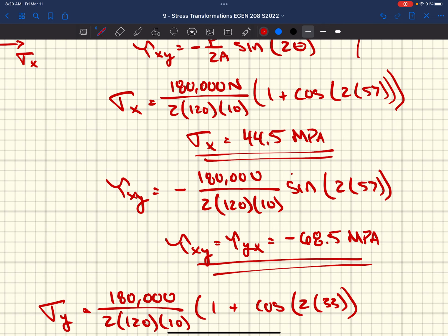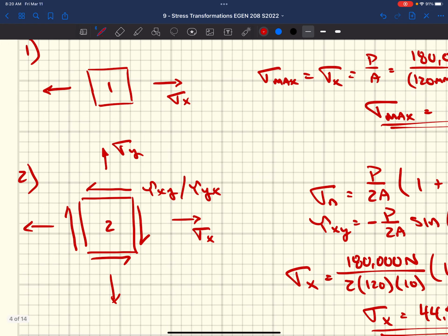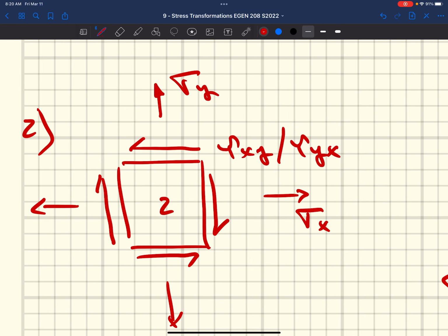So we knew based on that our shear stresses were going to face in this direction, right? Positive x face, the shear stress is acting in the negative direction. It's a negative shear stress. And we could establish all four of these. Really, knowing this one, we know what the rest of them are.